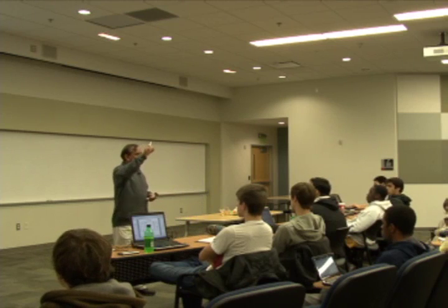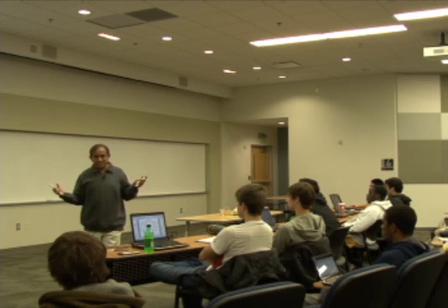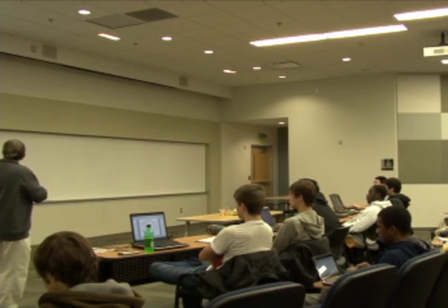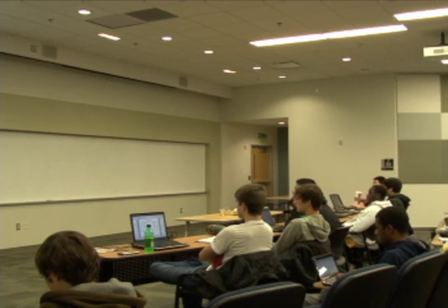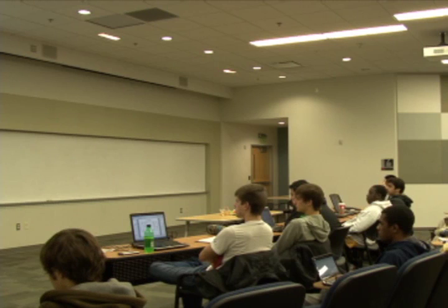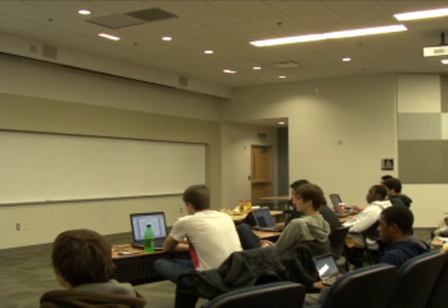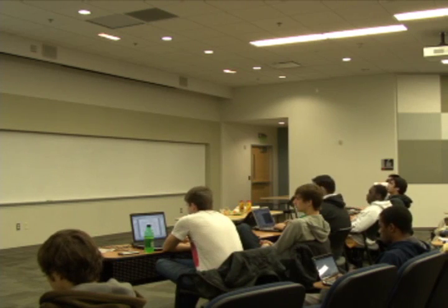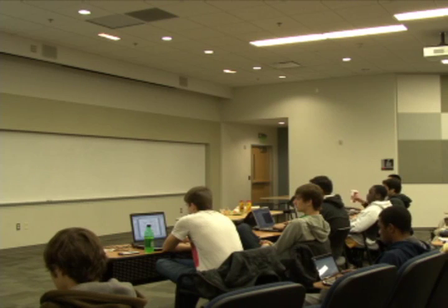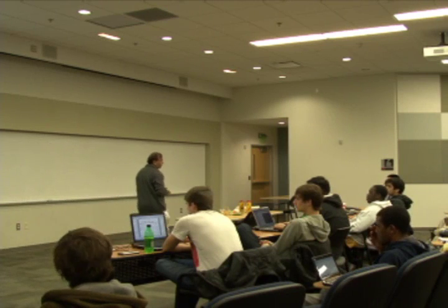Any questions on that? This is key for how you will implement your project one itself, right? So make sure that you understand how this works. Okay. So once I have that, then I can simply go to any number of these sequences. And once I go in here, then I can go sequentially through the micro sequence, because here it is a static determination what has to happen in the add 1 microstate, add 2 microstate, and so on till I finish the add micro sequence and then go back to fetch again. Everybody with me here on this? Okay. That's a very simple trick. And so once you have this, then I can implement this multi-way branch.